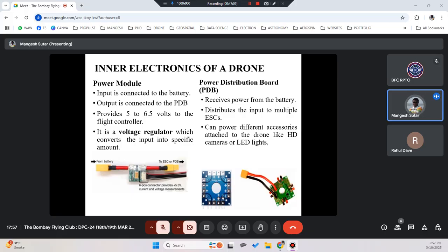Beyond that, we will always safely land the drone and replace the battery, because a threshold would be set at somewhere around 30% or 35%. There are various thresholds set based on your requirement, where you are actually flying, and how your battery performance is.